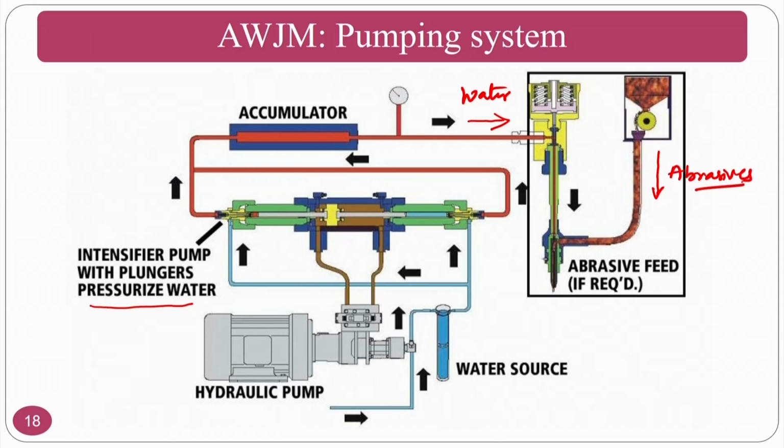So, the main important concept here is the intensifier, which intensifies, that means it increases the velocity of the water, or it increases the pressure so that it can impinge on the workpiece by mixing the abrasive particles and other things.